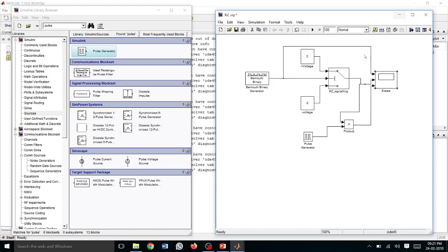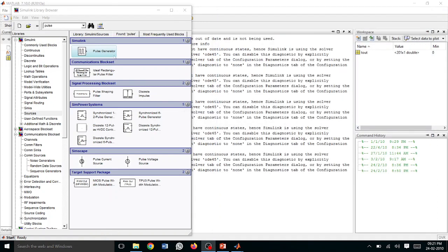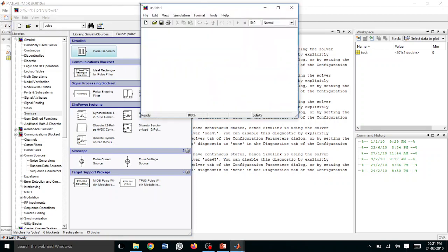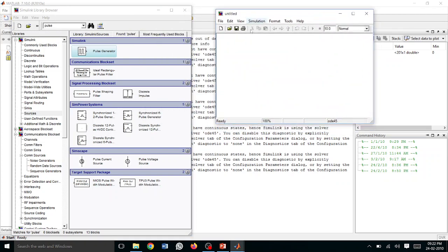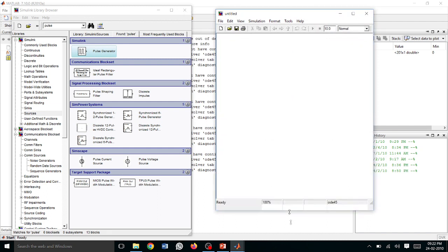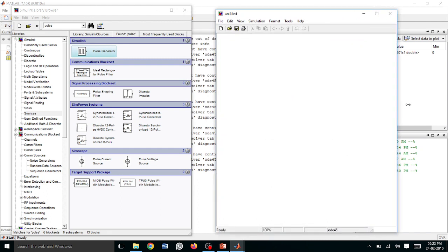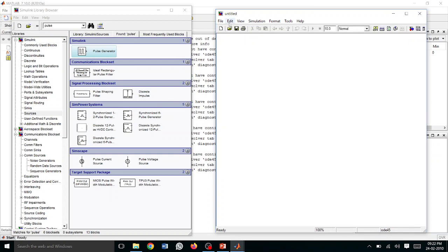Okay, so we have done NRZ signaling with eye diagram also, without eye diagrams also, then RZ signaling. Now the last experiment we will be doing is half sinusoidal. Half sinusoidal generation is nothing but something like a half wave rectifier. So we are going to give input as a full sine wave, but we have to get a half sine wave.